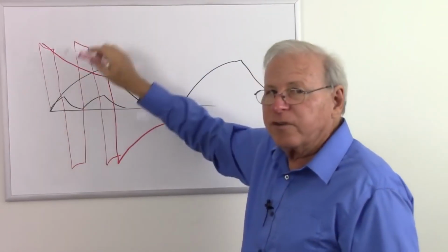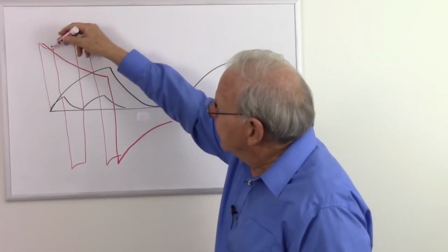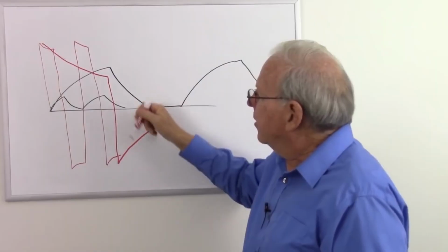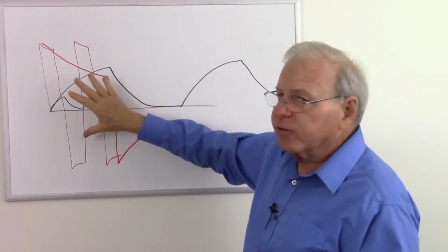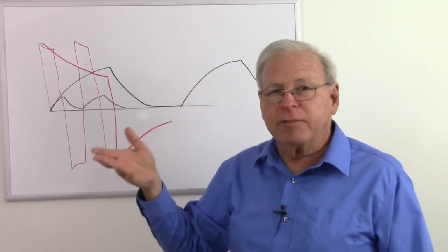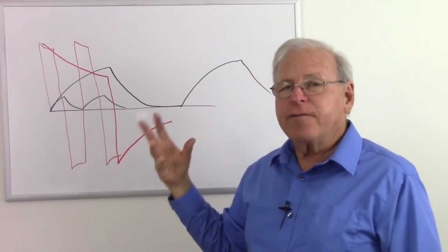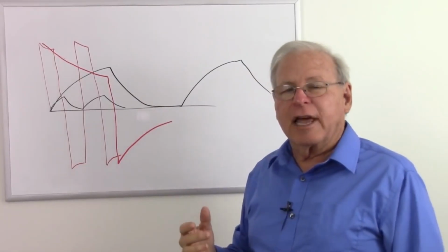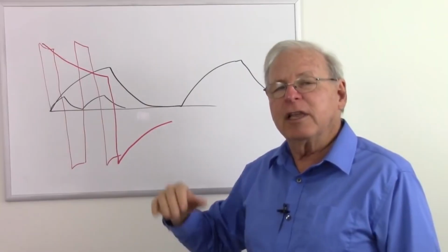So if I flip the switch fast or quickly at a high frequency, I spend more time in a high current state and I don't have time to go to a low current state. But if I flip the switch slowly, it has time to go to a low current state. So the faster I flip the switch, the more current I got through the capacitor. So at a higher frequency, the capacitor looked like a smaller resistor. High frequency, more current. Low frequency, less current.